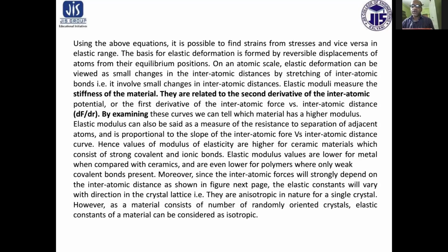The basis of elastic deformation is the reversible displacement of atoms from their equilibrium position. On an atomic scale, elastic deformation can be viewed as a small change in the interatomic distance by stretching of interatomic bonds. That is, it involves small changes in interatomic distances.